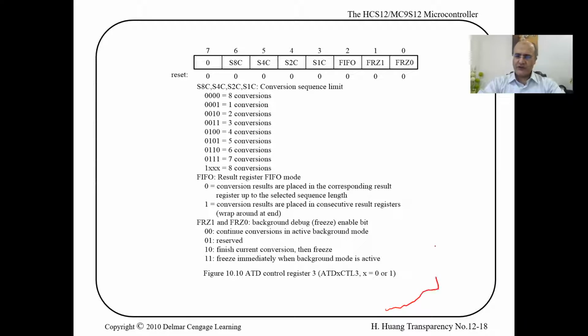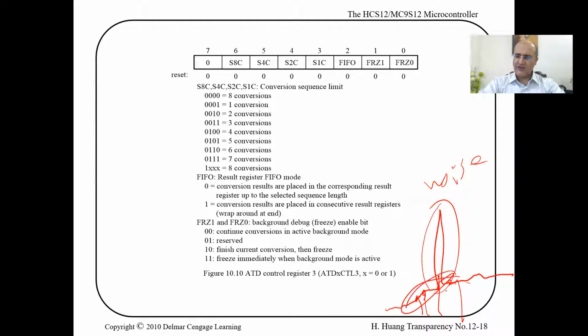You're reading a voltage. Sometimes you can get a spike, which is probably noise. So sometimes you can do this manually. You read the A to D maybe 10 times. Then you average them. Averaging them is like you're reducing the importance or the contribution of this spike, which is something like doing a low pass filter, right? Actually, averaging is a low pass filter, right?